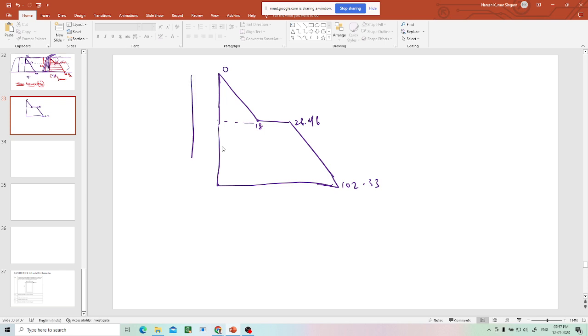There is a wall here. There is a pressure value, these are kPa. Now the wall is like this. You can take some area. This is the area on which this is acting, and the remaining bottom area is this one. But on this area you cannot take 18, you cannot take 0. You have to take the average value, average pressure multiplied by this area.